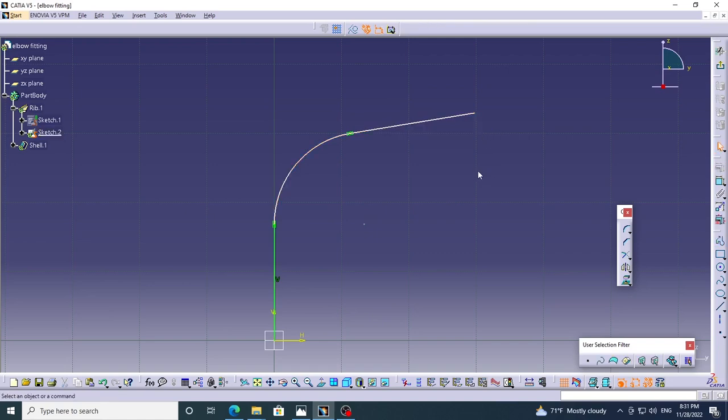So to define the 75 degree, I select profile and I draw two lines from tangent points to center of the arc. The important thing is that you should select these two lines and make them construction elements. It means these two lines are not part of our sketch. If you don't do it, you won't be able to use Rib tool.